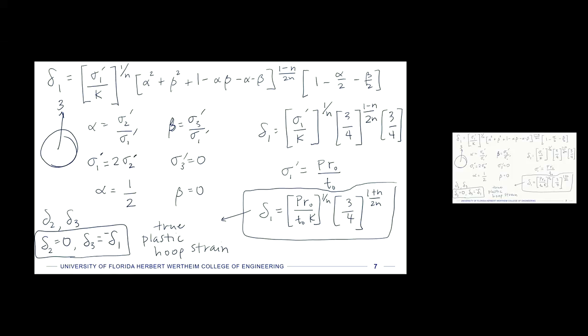So we're going to take the derivative of pressure now with respect to these plastic strains and see when that's 0, what is the pressure at that point. We'll solve for that pressure. We can't quite do it just yet because if we look up a material, we can get K and N, but right now all we have is R and R naught and T naught.